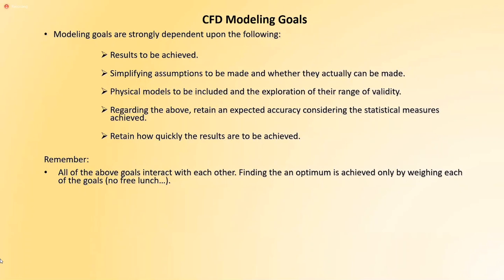We never want to start a project when all we think about is, do we have the computational resources for that? And I don't mean, I decided I want to do a DNS of an airplane. I mean simple CFD, Reynolds average Navier-Stokes. You should be able to do it with almost every geometry. If you find yourself all the time fighting with computational resources, get a better computer.